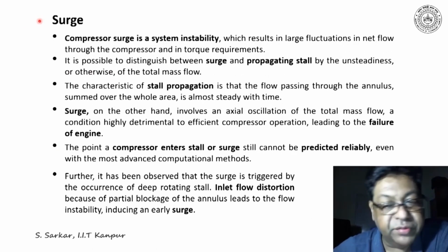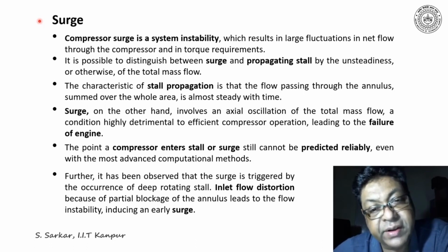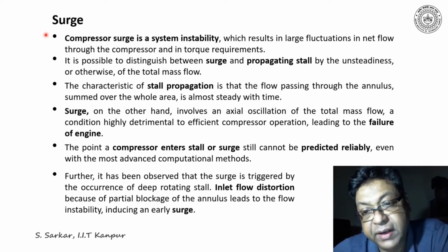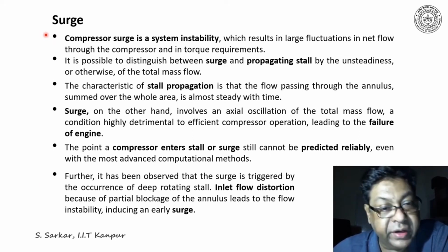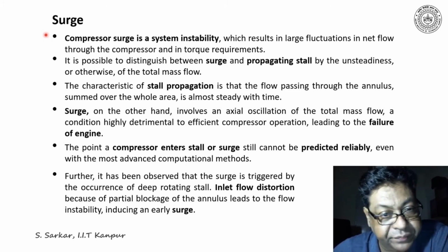Let me discuss surge in brief. The compressor surge is a system instability which results in large fluctuation in net flow rate through the compressor and in torque requirements.